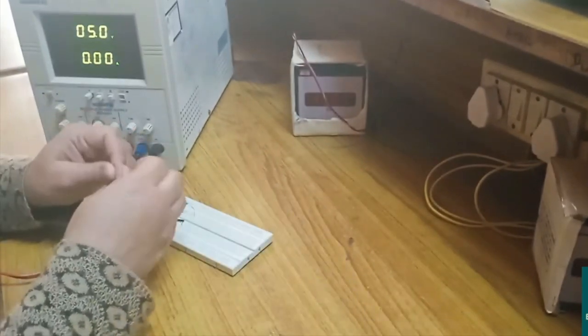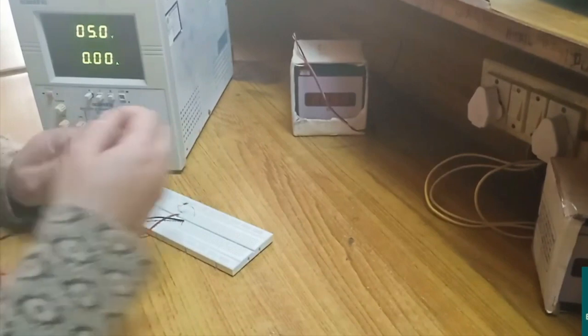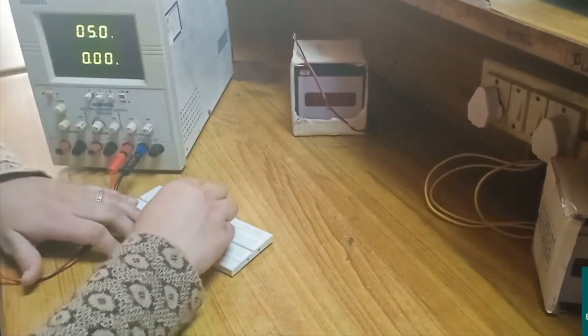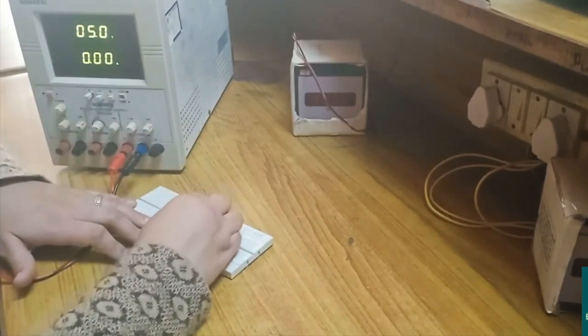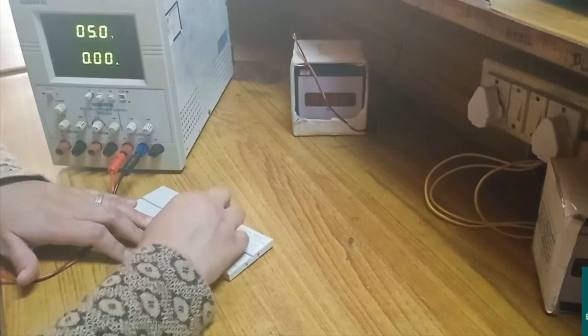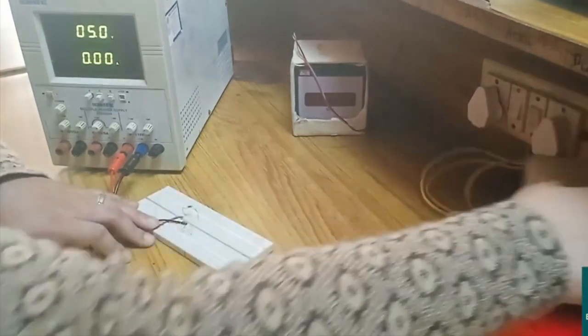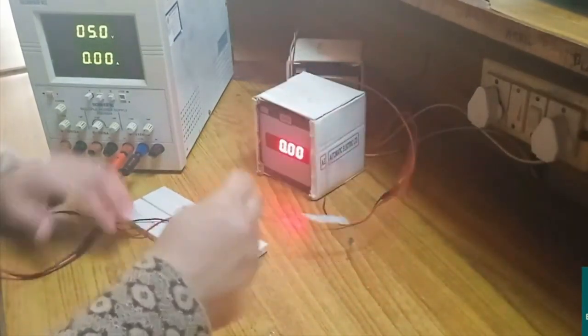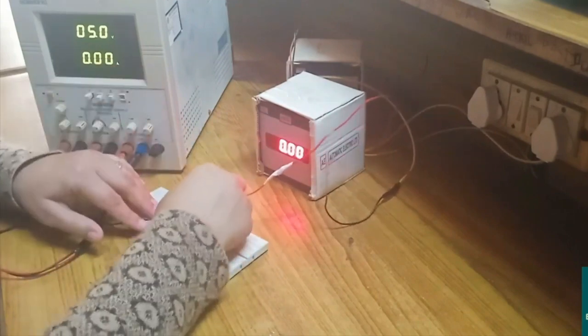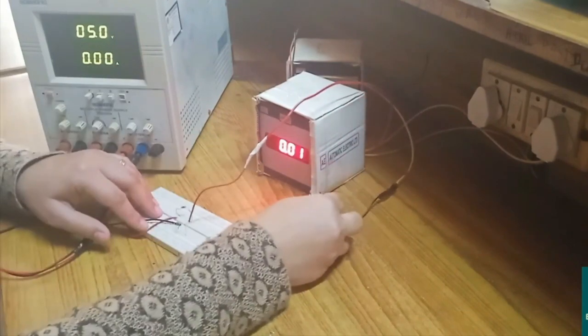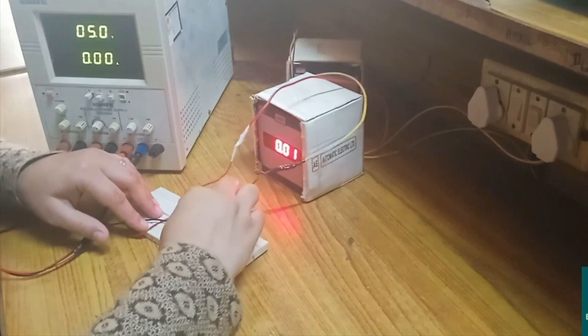So RL 1 kilo ohm, this 1 kilo ohm. But yes, we need to calculate current as well. So the ammeter will also be connected in the same series connection. So let us again use this ammeter over here. The positive will be connected with RTH, negative will be connected with RL.